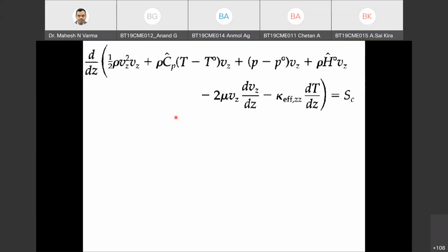Here we are considering temperature variation, and pressure has a role to play in temperature through viscous heating, as we discussed yesterday. Because velocity is constant with respect to Z, pressure is negligibly small to contribute to any heat changes in Z direction, hence P is considered constant with respect to Z.